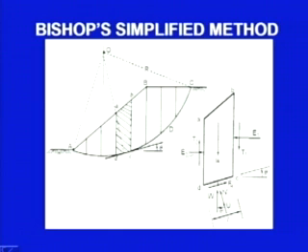As a whole, when you do the analysis, the force T2 you see is acting in the upward direction for this slice. So, T2 here is acting in the upward direction for this slice. When we consider the next slice, this one, the same T2 will be acting in the downward direction.